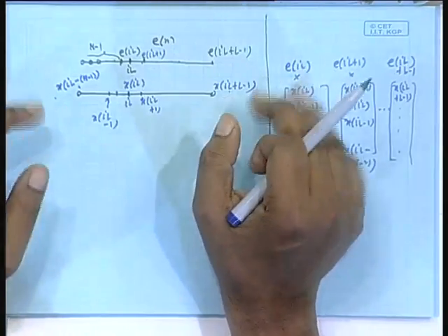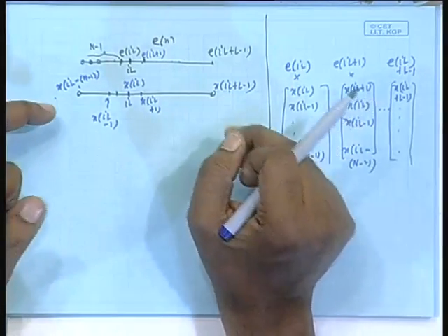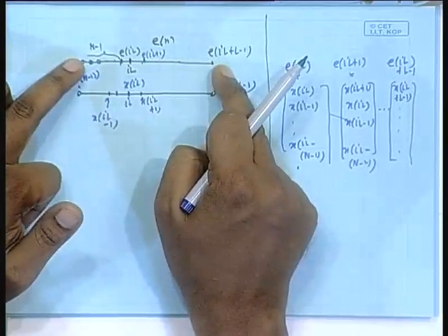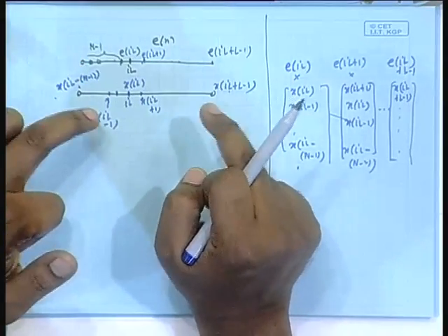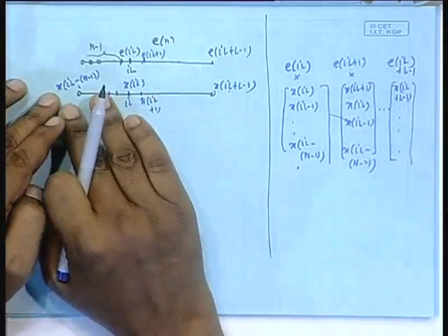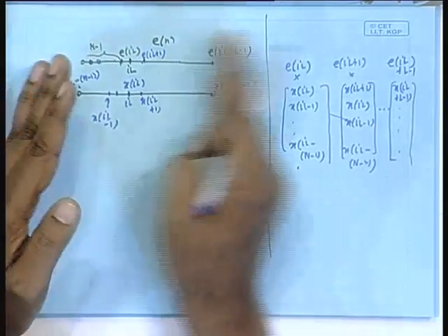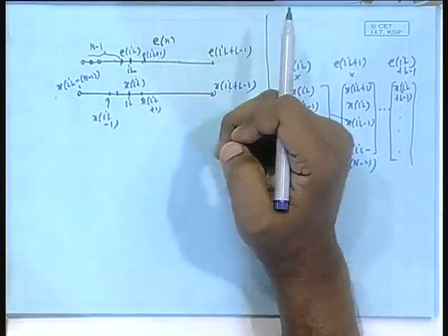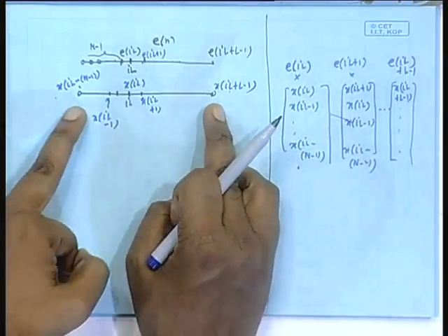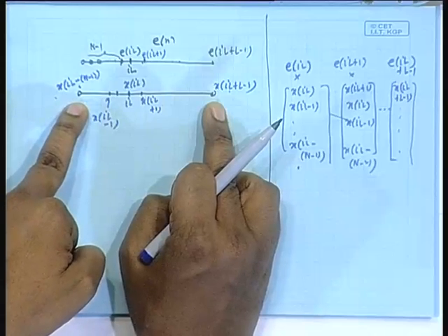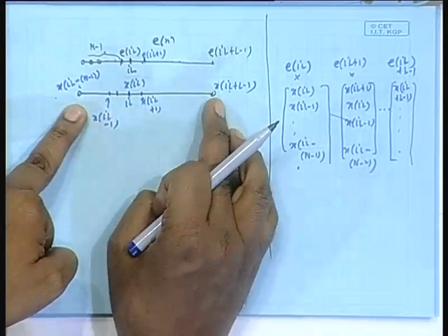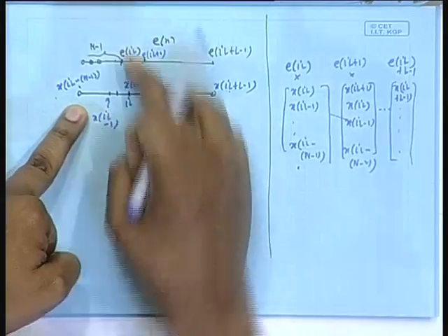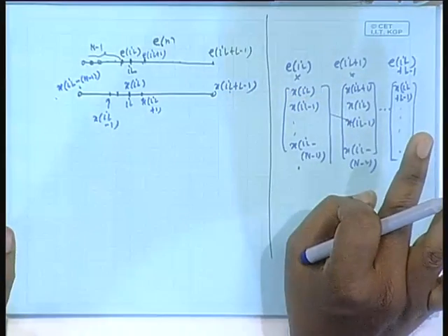Isn't it. So, you remember that this is something what we do in circular convolution. What do we do in circular convolution? One sequence I hold as it is, other sequence I make a periodic version, reverse, I shift and chop off the right and left and do sample wise multiplication. So, that means with 0 shift, but after reversal, if you multiply sample wise you get the first entry of the vector, isn't it.